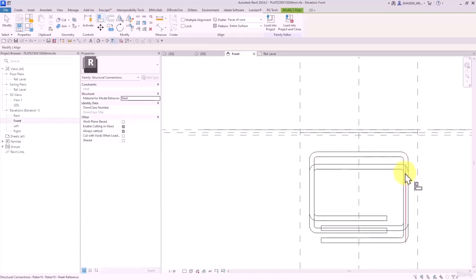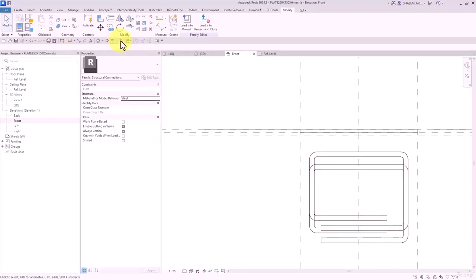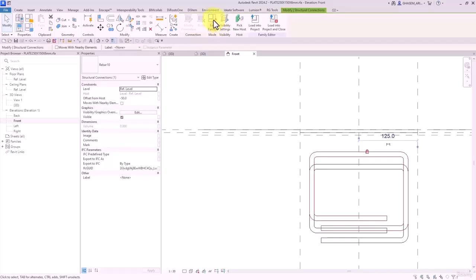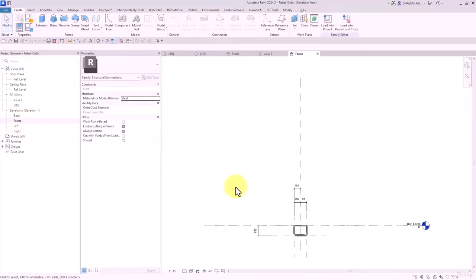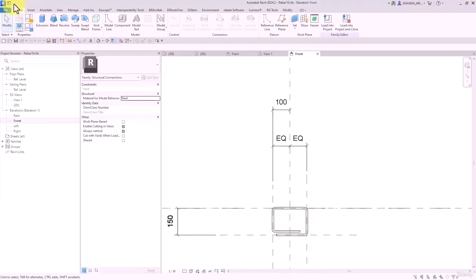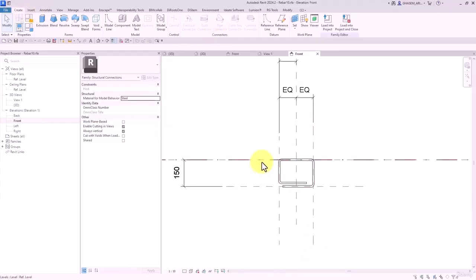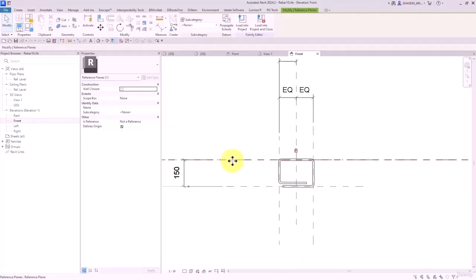Here, I can't select this middle part. It has an interesting technique which we can use. Here in this family, this part is not visible. The reason is that the reference which we have here is not a strong reference.